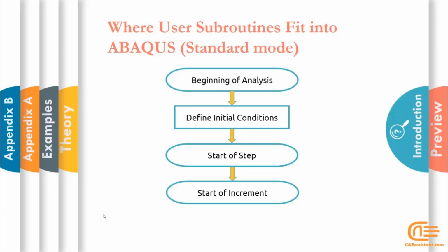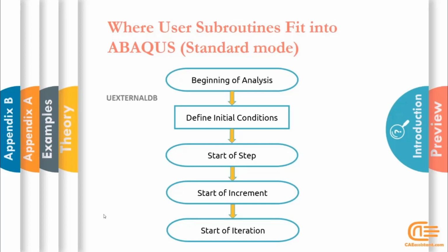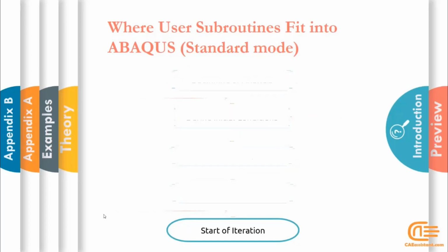As you know, in the case of an implicit solver, we seek the equilibrium at every increment by checking the difference between externally applied force and internal reaction force. This difference is called residual. Abaqus uses a tolerance value close to 0 defined in its solver setting. Till the difference between the forces comes under this tolerance value, the solver carries out several iterations. Therefore, Abaqus carries out iterations within an increment in order to attain equilibrium.